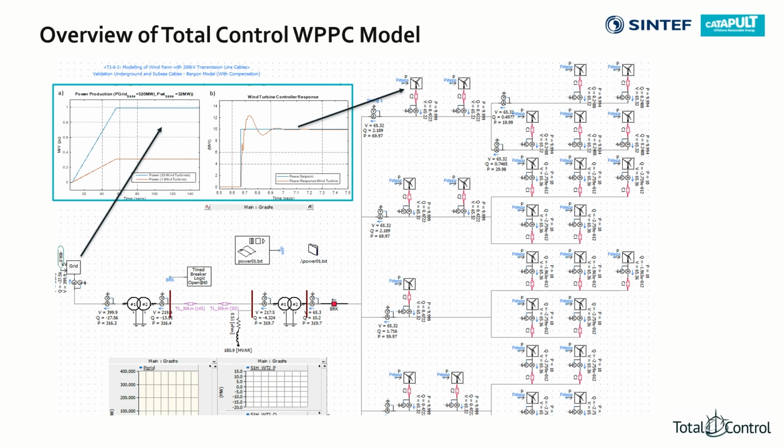And you have a 320 megawatt model there with about 32 turbines, which are all interacting together in an electrical system design, including the aeromechanical side of things, bringing in wind speeds as well. The diagrams there are just an example of a power production mode scenario being run.